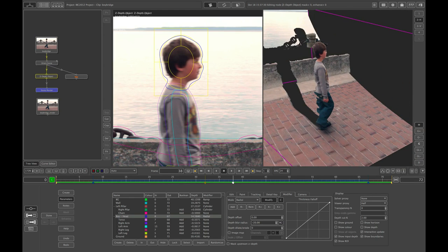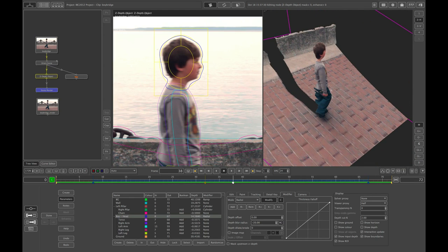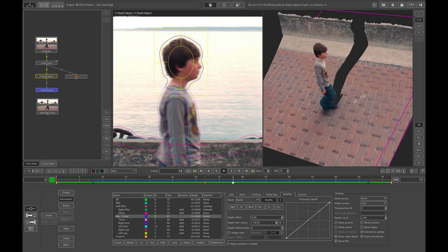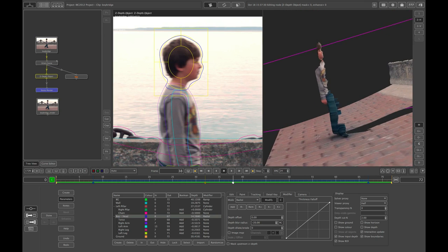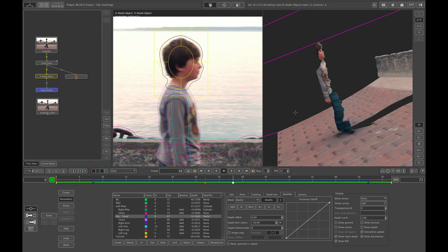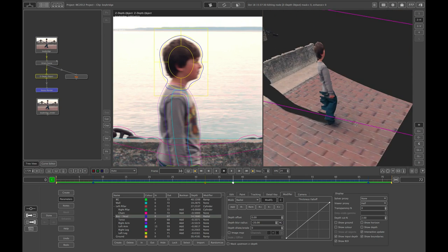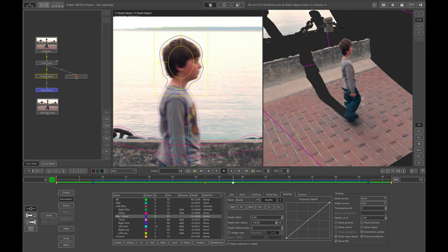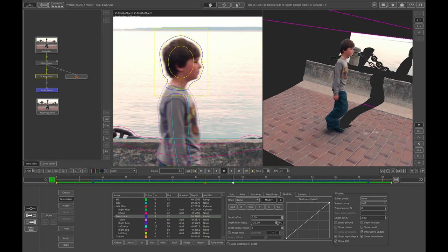So it's going to help us in two things. One, it's going to give the illusion that there is some actual dimensionality to what is otherwise a postcard in space. And the other thing is it's going to help with things like inpainting, because what we have is a curved surface now. So when we bring this into our stereo render node to create our second camera view, there's actually a surface now that the second eye camera is shooting across.